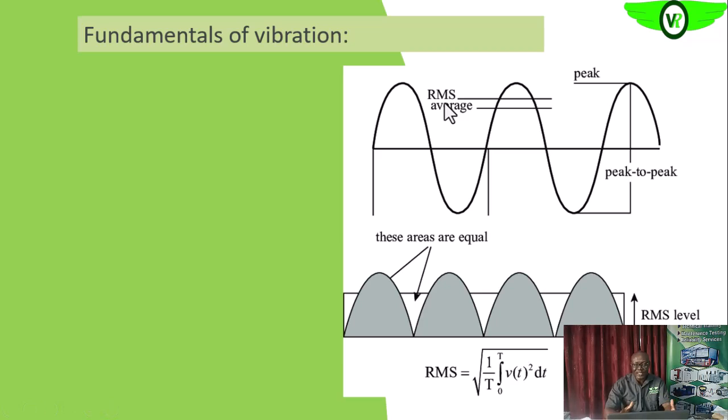Which means that for the sample data, we square each of these samples, add them together, take the mean of that squared and added sample, then we take the root. That is the root mean square value of the sampled data.